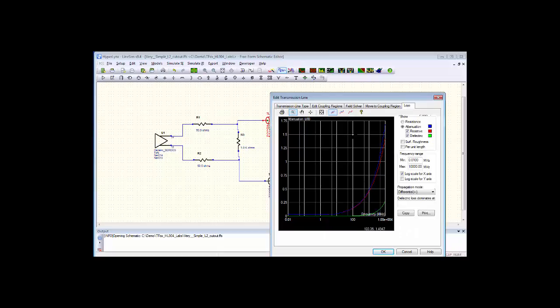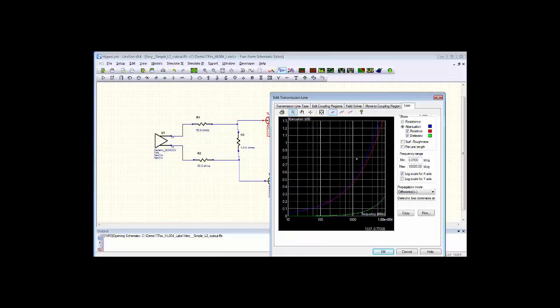Now look at it, and I'll go back to 1.25, zoom in on this, and now if I get out to 4 gigahertz, instead of being 1.07, I'm at 1.007. So in other words, going wider gave me less loss in the line, and that loss that I picked up was basically the crosstalk loss.